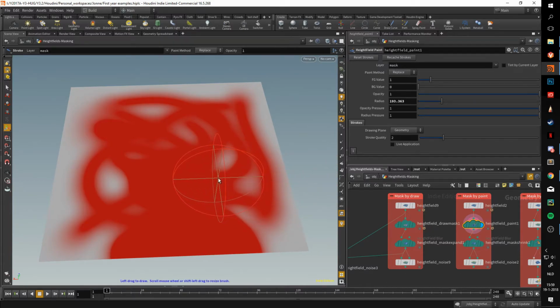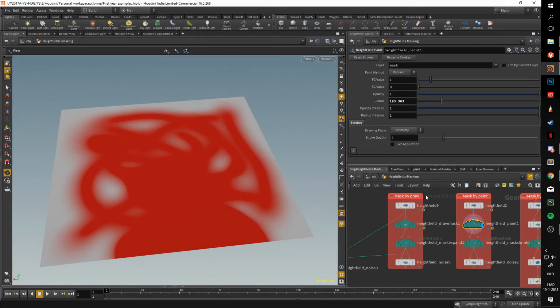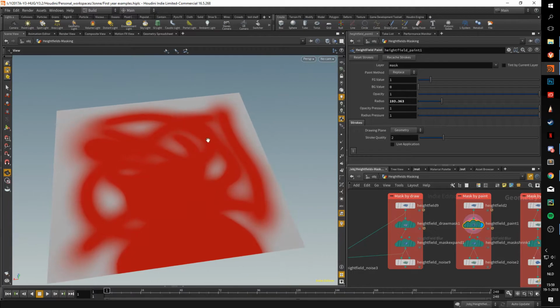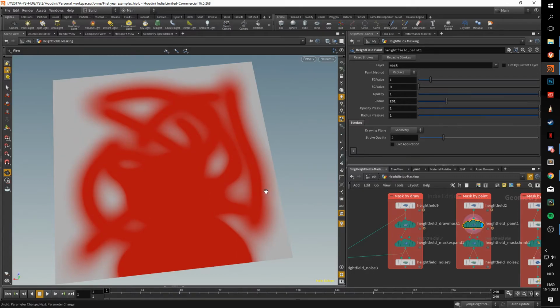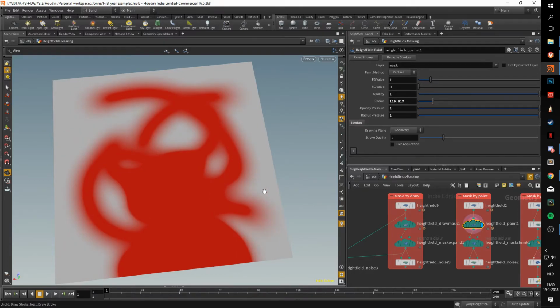And if we press escape in our viewport, with our mouse in the viewport, you can see this widget disappear and we're going back to the normal editing mode. But let's say we have this mask, but we think it's too large. We want to kind of shrink it a bit. Well, Houdini has you covered with a Heightfield mask shrink. If we display this, it doesn't do a lot right now. So let's actually Control Z a bunch to remove a lot of these clutter lines.